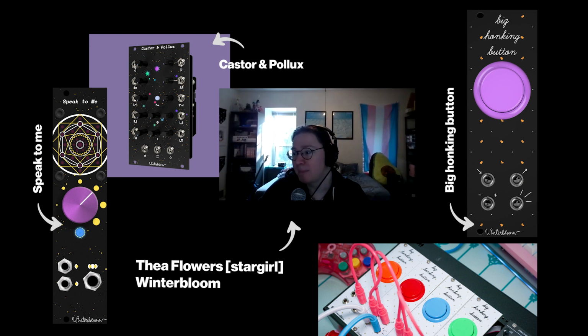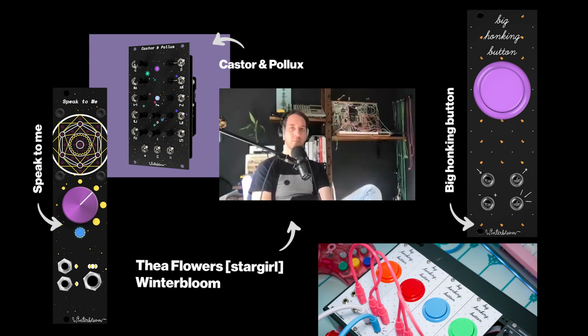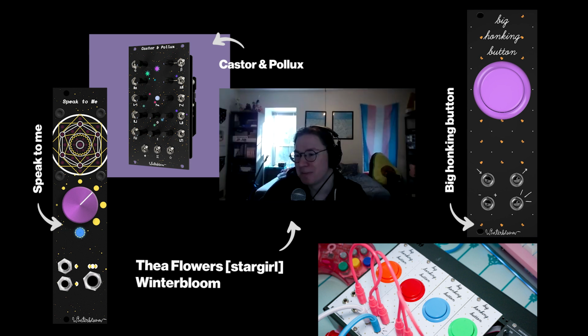Some headphone amplifiers can just deal with that, and they don't care. This particular one, because it's designed to deal with higher impedance headphones, will actually end up driving that output pretty high and causing itself to overheat. So there are some thermal protection resistors in there to keep things from getting out of control. And it's just something I didn't catch until into validation testing, where it's like, oh no, this one tiny edge case, and I want to make sure that it works. So yeah.